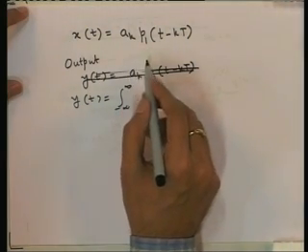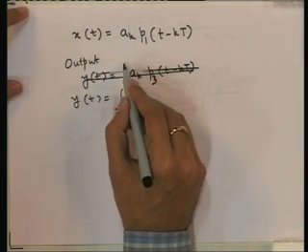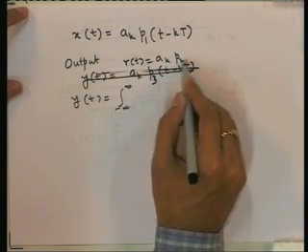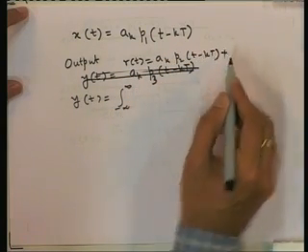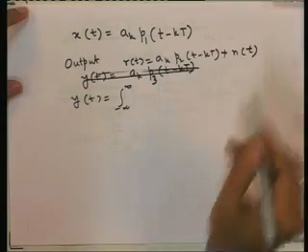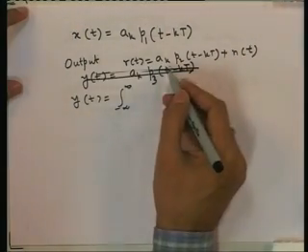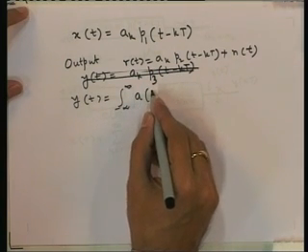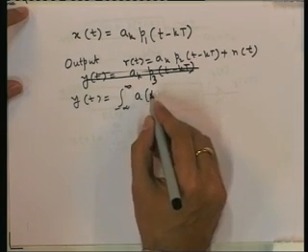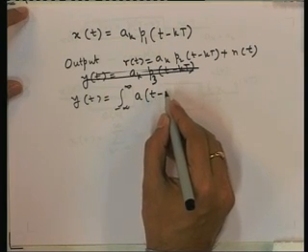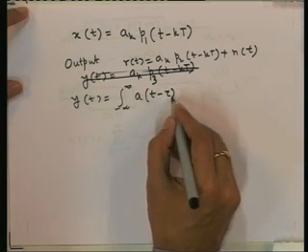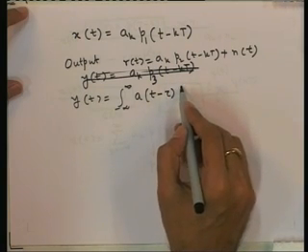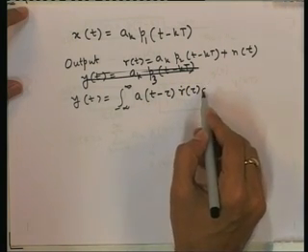At the receiver, before the receive filter, we will receive r(t) equal to a_k p2(t minus kT) plus n(t). Then we pass it through the receive filter a(t). So we will get a convolution output, integral of a(t minus tau) r(tau) d tau.